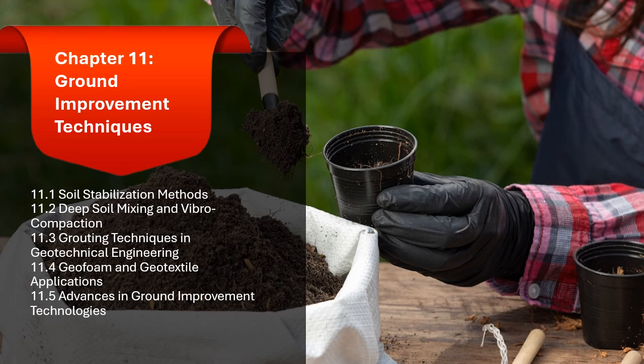1.1.4 Thermal stabilization. Thermal stabilization involves the use of heat to alter the properties of certain soils, particularly those containing expansive clay minerals. By applying heat, the soil's moisture content is reduced, and its physical properties are modified to make it more stable.